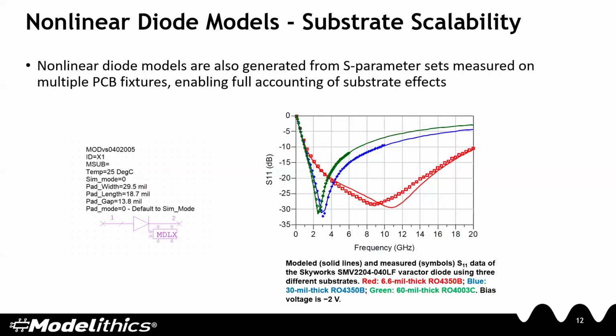But you can see again how the performance changes as we vary the substrate. So again, that's a very important aspect, is that the performance does depend on the substrate that it is mounted on. And these nonlinear diode models do capture that substrate scalability.